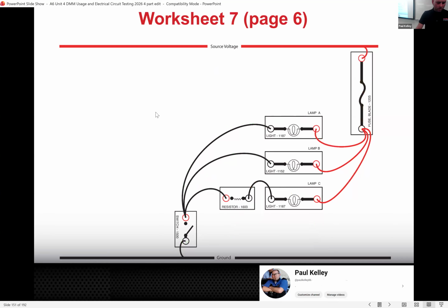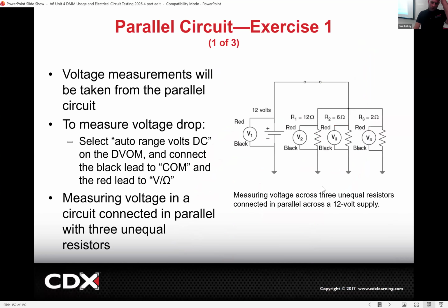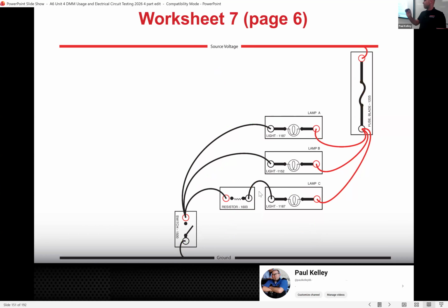And that's essentially how we would diagnose a series circuit, even a parallel circuit, even if it had a little mini series part in it. Cool? So if the bulb is dim, it may have unwanted resistance, but it would only have unwanted resistance in the part of the circuit that would affect that particular bulb, right? If this bulb is dim, we're not worried about high resistance on the fuse. What if we had high resistance on the fuse? Which bulbs would be affected?